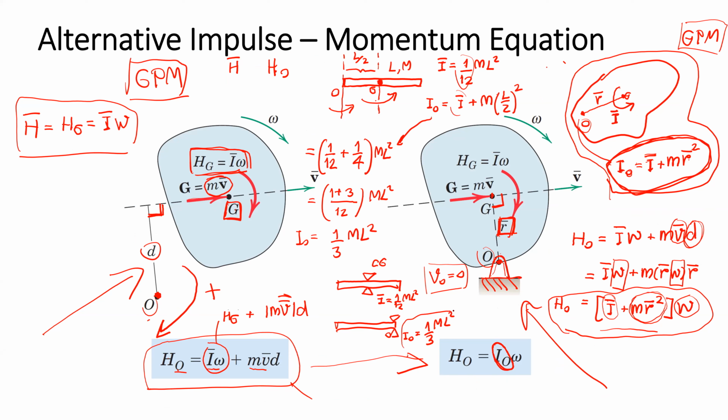So yes, by the feeling, you can see some difference. Actually, it's a huge difference. If you change the position, you can see the huge difference in the inertia property. In the first case, I bar is the inertia property to resist the motion, the rotation. I, moment of inertia, resist rotation.